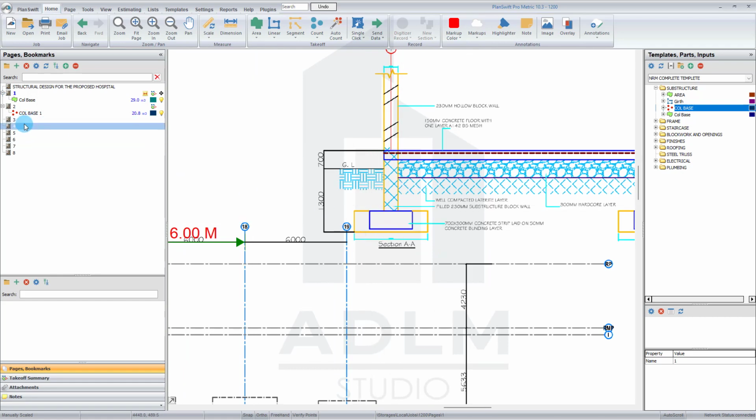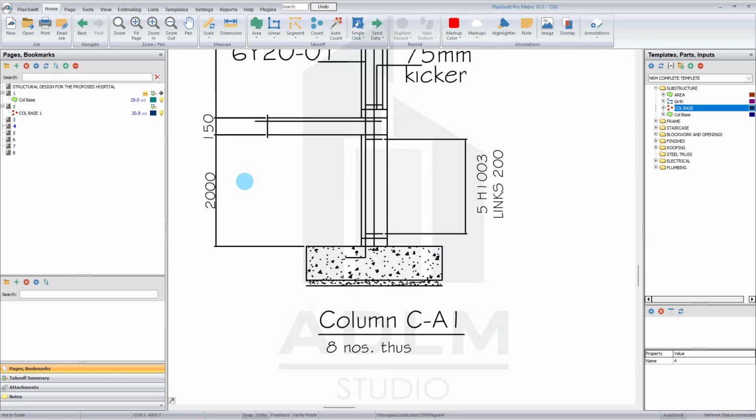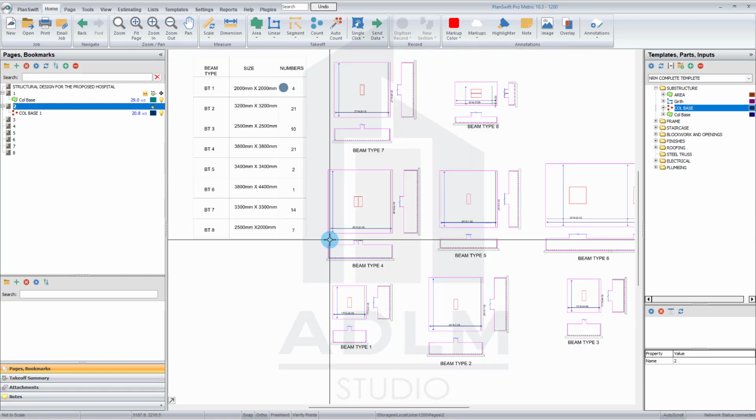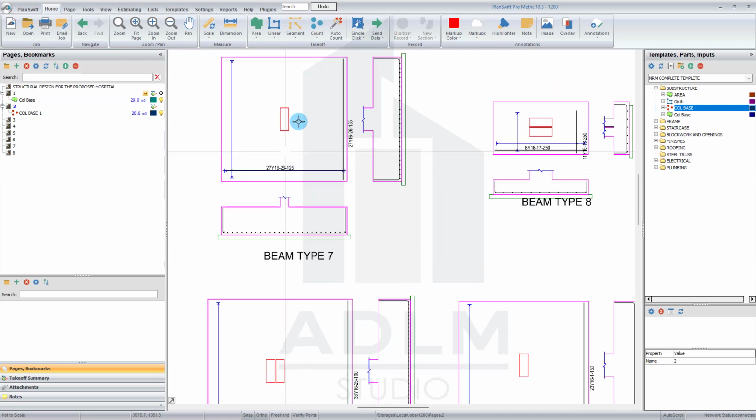Now let's see the column base details. Now we have this here. So for the total column base, it's around 2 meters, including the thickness of the base of around 800 mm. So we're to add the thickness and all and the blinding, which is shown on this page here. That should be around 2.8 or 2.6. And I can always verify that by using the scale.